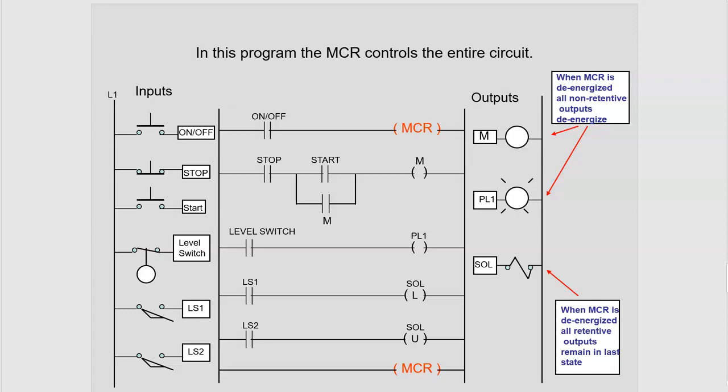That's important to know, because when you start the system back up, it's going to start with that retentive output as a high. And usually you don't want that, for safety's sake. You usually don't want that when you turn the master power or master switch back on. Imagine your house. At your house you have a main breaker. If you ever had your electricity turned on in a new place where you move, the electric company always tells you to make sure that the breakers are in the off position.